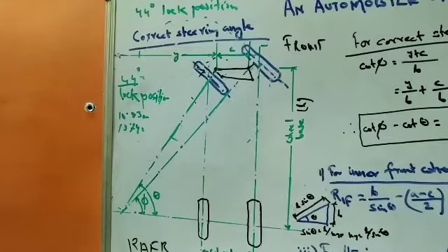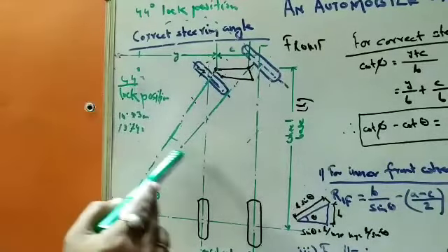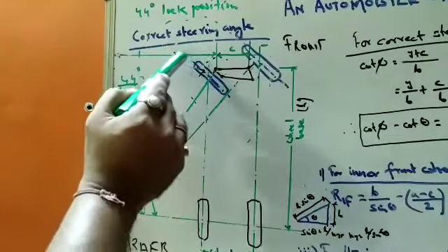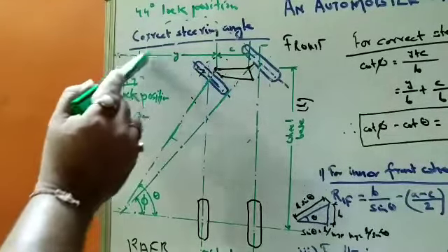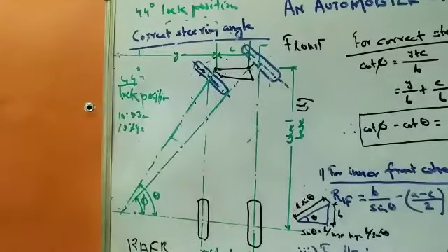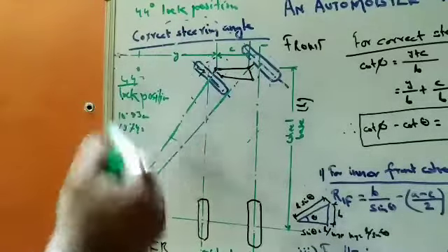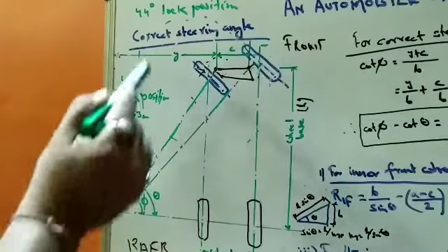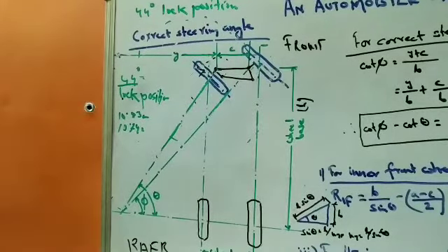The smallest circle the outer wheel can cover when the wheels are at the extreme condition is known as the turning circle, and the radius is called the turning radius, which is an important parameter for different vehicles, because nowadays very little space is available for turning. So this is an important criterion.